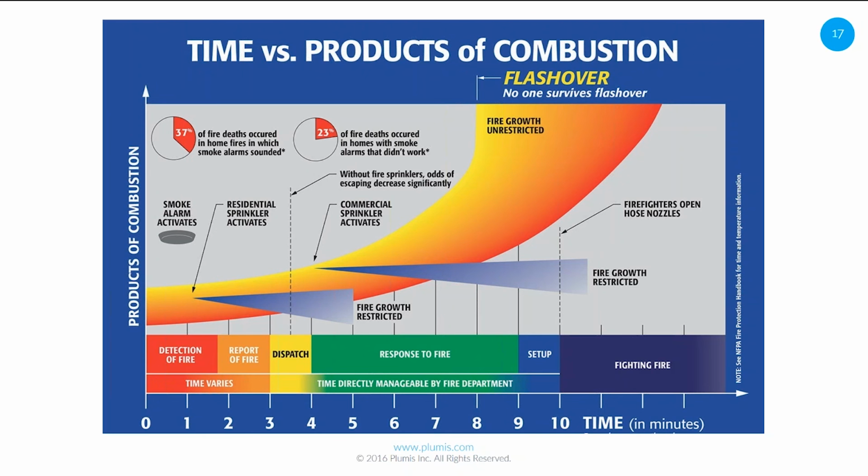For all of the positive effects of a smoke alarm, it is not doing anything to control the event. It's doing nothing to suppress that fire. So we need to look at alternatives. What can we do to help mitigate that risk at that point when we have this high-risk audience present who cannot promptly self-evacuate, which is contrary to that primary assumption that's made in the typical design and construction of a single-family dwelling.